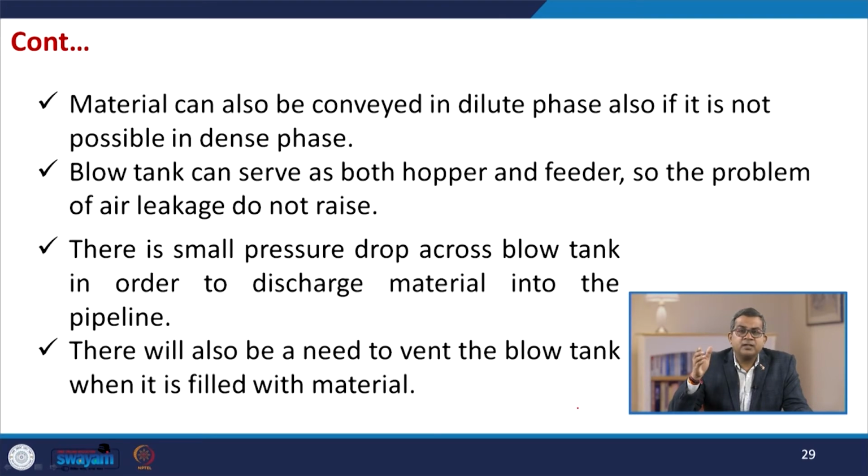Blow tanks can serve as both hopper and feeder. So, you cannot experience the problem of air leakage in the blow tank. Usually there is a small pressure drop across the blow tank in order to discharge material into the pipeline.